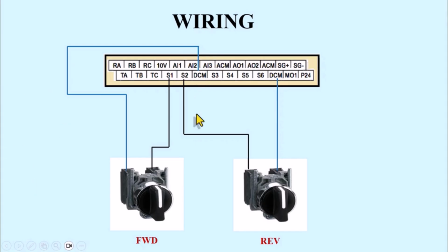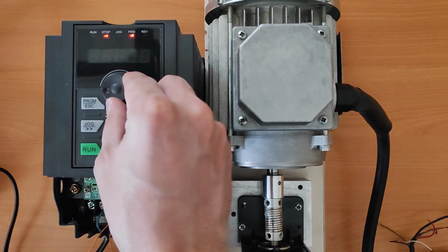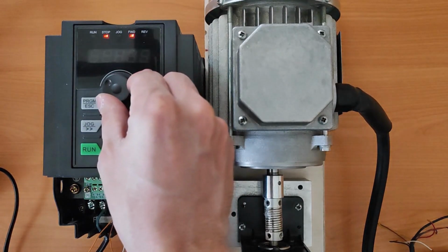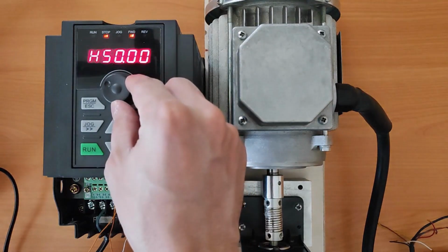Now let's go to the BD600 inverter settings. Let's apply the settings we've learned and test it together in this instructional video. We said that we should set the frequency reference mode to the potentiometer built into the inverter's keypad so we can change the output frequency of the inverter using this knob.